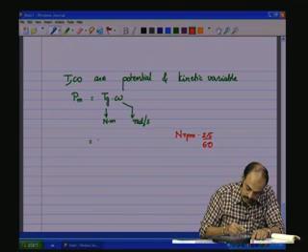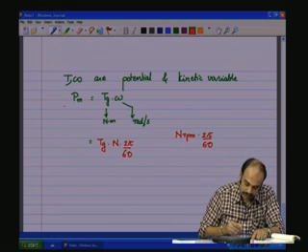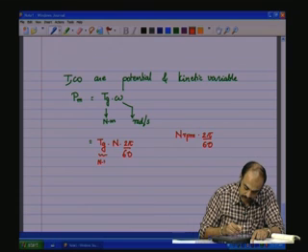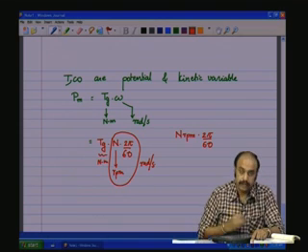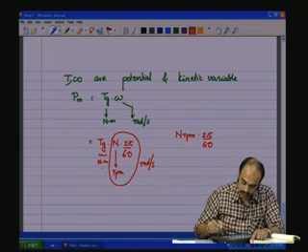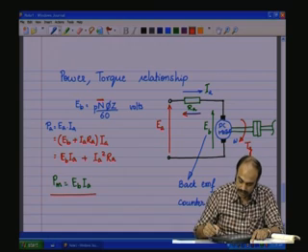So, therefore, Tg into n into 2 pi by 60 will give you the power. So, this is in Newton meter, this is in RPM, and this whole together is radian per second. Okay, equating this along with this, we have